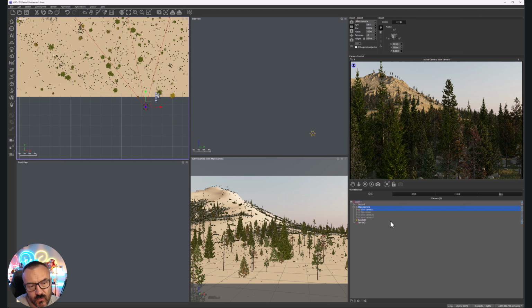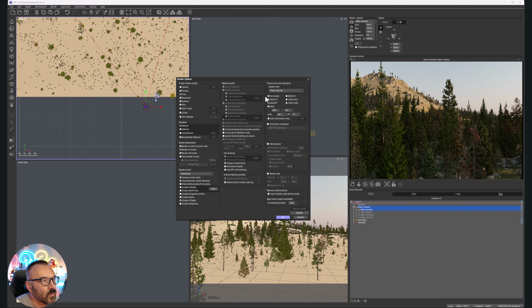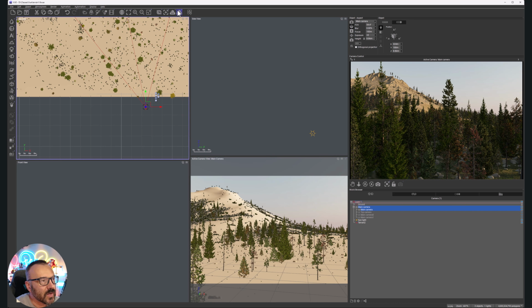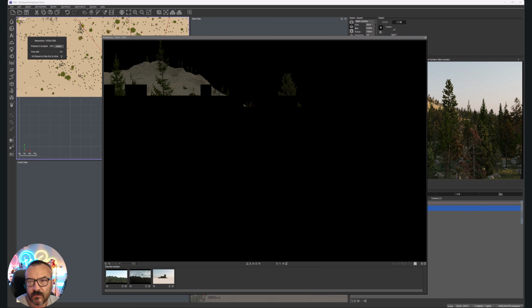Well, the next thing, let's go just to render. So I'm going to render maybe different camera views. We'll start with this. We'll right click, render, final, at least. Turn on, we render to the screen. And we'll just go HD resolution. Again, because I don't have clouds, it should render quite a bit faster. Let's click OK and click render. So we'll see how long it will take.